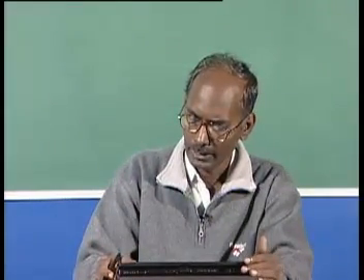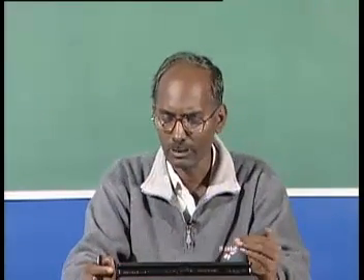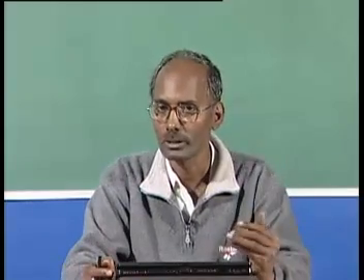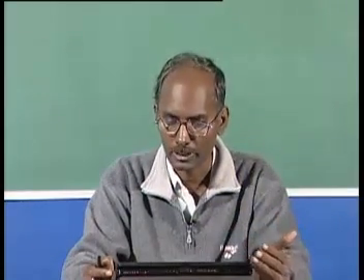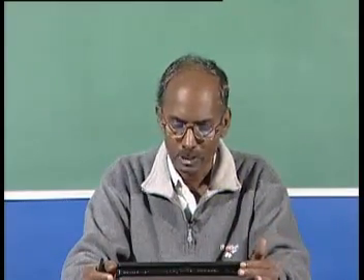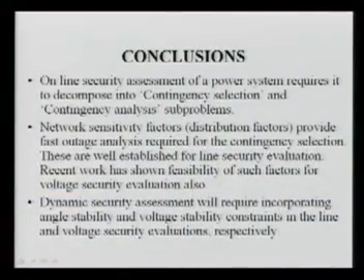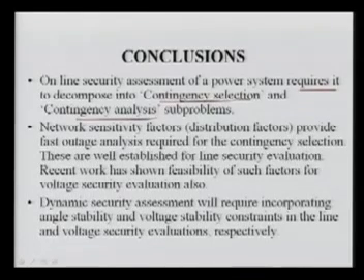Now I can just conclude, and then we'll give some more highlights on what we are going to have next in this contingency security analysis. Online security assessment of a power system requires it to be decomposed into the contingency selection and the contingency analysis problems. Once again, these contingency selection and contingency analysis problems can be combined together if you have a very fast computational algorithm along with a fast computational platform.